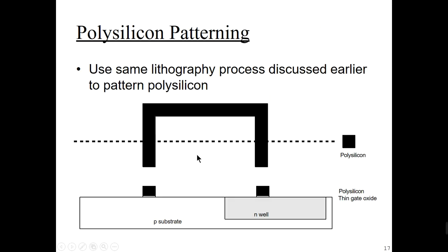And after that, polysilicon has to be placed where I want to design the gate terminal. The main intention is to place the polysilicon at the place where we want to make the gate terminal. In CMOS transistors we have an NMOS transistor as well as a PMOS transistor. For both NMOS and PMOS transistors we have one gate terminal. Each transistor uses one gate, that's why polysilicon has to be placed here for one transistor, and this is for one more transistor. In the N-well process we can place a PMOS transistor, and in the remaining second case we are using an NMOS transistor.